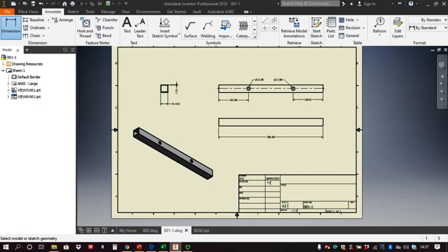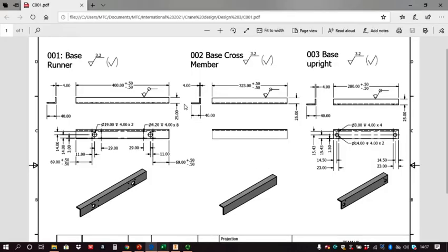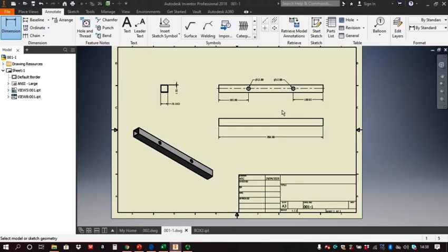Some things that you do, you may require 4, 5, maybe even 6 views, although 6 is quite rare unless you're CNC milling. Okay, so going back to this drawing, I've put 3 views in here. Why 3 views in this one? Well, this side differs to this side, so it's probably safer to say, look, they're all there. But also because of the way the end profiles are set, the whole detail is in the 3rd view, so I couldn't really get away with 2. Okay, back to this drawing, I could get away with 2.